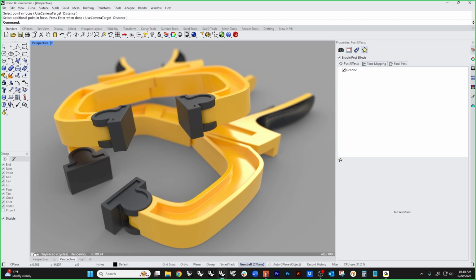Oh, good question. When I 3D print and it has soft edges, does it do them? No, unless you use a command called extract render mesh. What it does is it takes the render mesh that has the softening on it and extracts that into a real mesh that you can then print.